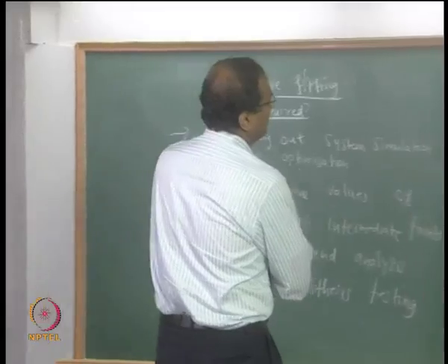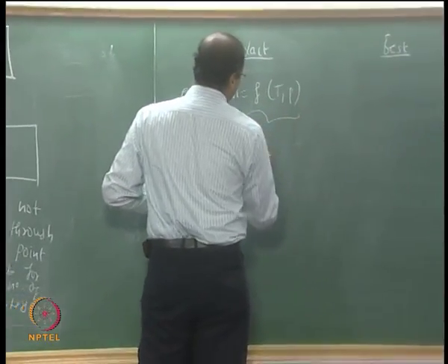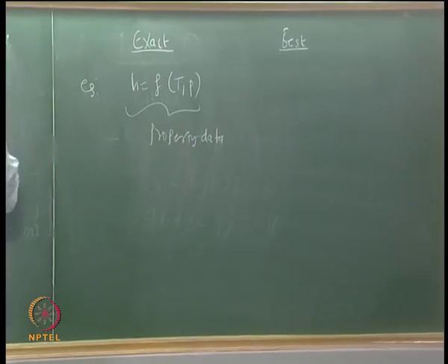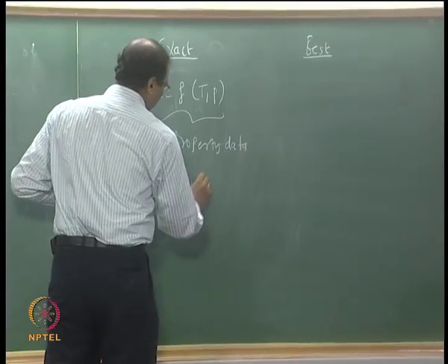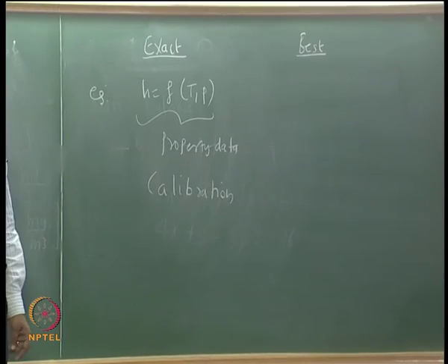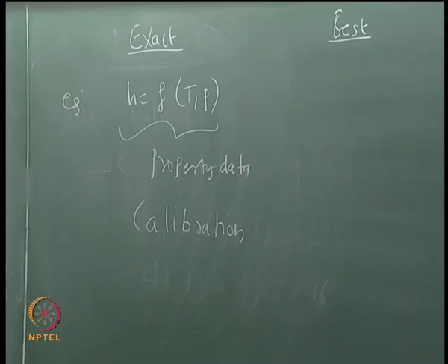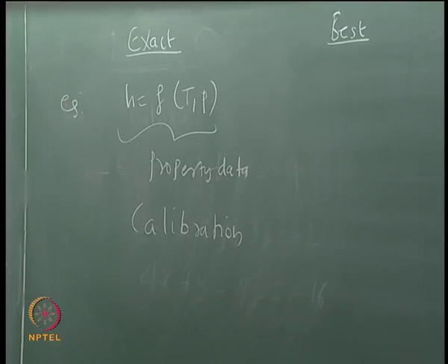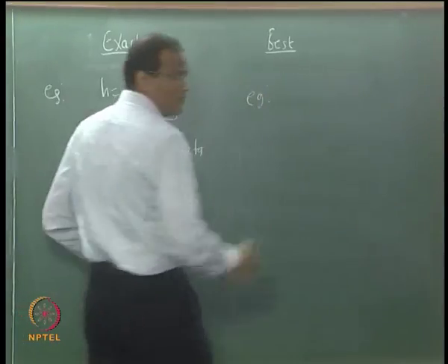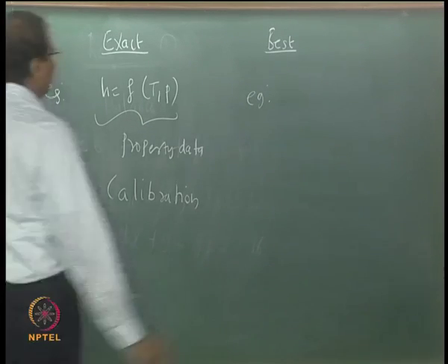Now, if you want something, enthalpy is equal to a function of temperature and pressure. So, for property data like this, you can go for some exact fit. Calibration data, okay, what is that calibration data? Thermocouple EMF versus temperature, where everything is highly accurate, then you can have an exact fit. Here, any regression,